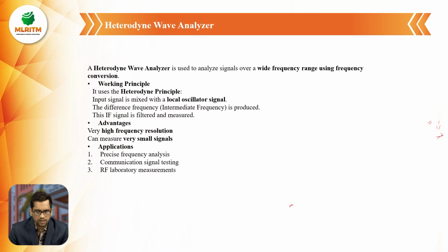What is the other important application of heterodyne wave analyzers? RF laboratory measurements. Mainly these heterodyne wave analyzers are used in RF laboratory equipment testing and signal analysis. Why? Because heterodyne wave analyzers have high frequency resolution with very small signal quantity measurement.